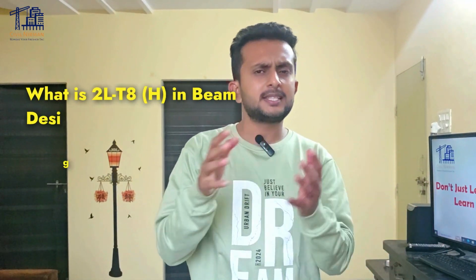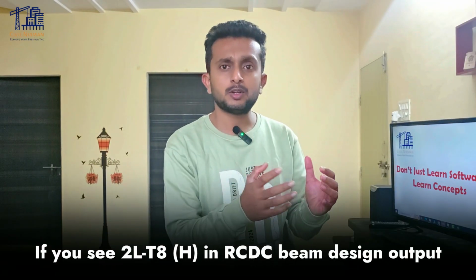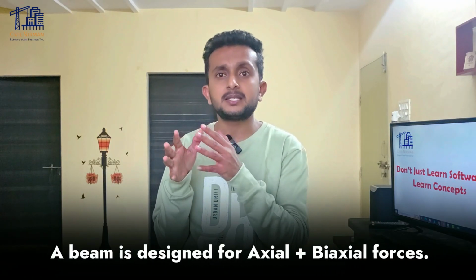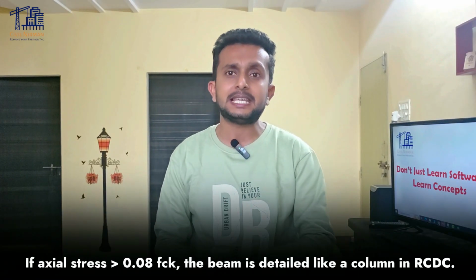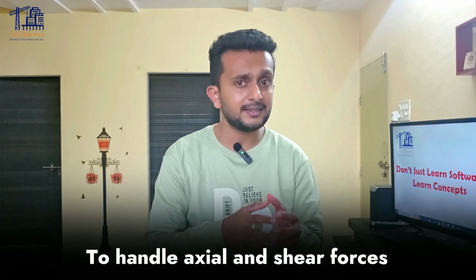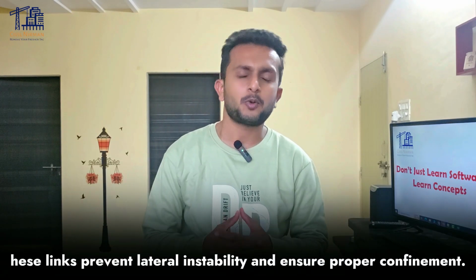Next question, what is this 2L-T8H in beam design output? Now if you see this particular notation in the RCDC beam design output, it refers to the horizontal links, that is your stirrups. It is used when a beam is designed for axial plus biaxial forces. Now the next question will be, why are horizontal links needed? If axial stress exceeds 0.08 fck, the beam is detailed like a column in RCDC. Horizontal links tie all the rebars along all faces to handle these axial and shear forces. These links prevent lateral instability and ensure proper confinement.